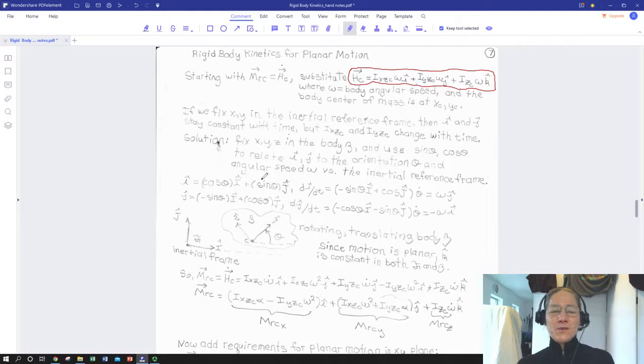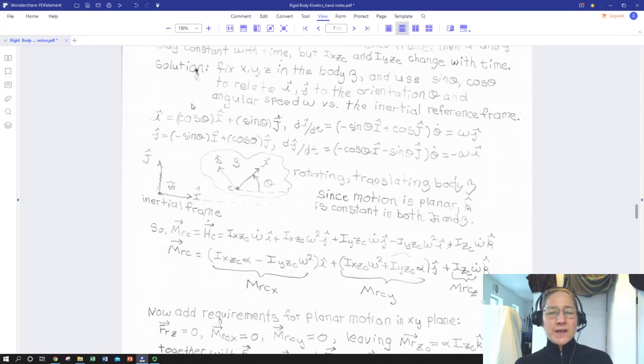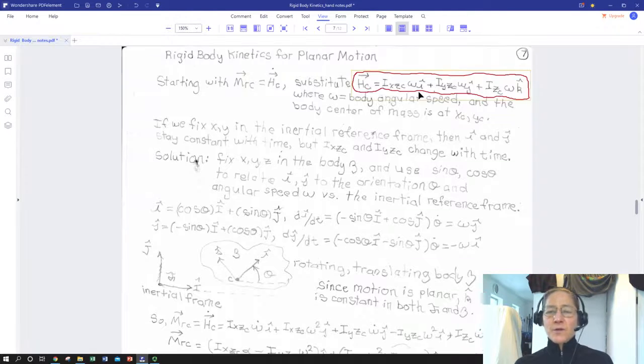So what we're going to do is fix the inertial properties of the rigid body to a coordinate system that is fixed on the body, not the reference inertial frame wherever it is, usually outside the body, but it doesn't have to be. So let's go down and blow this figure up a little bit. This is a bit esoteric, but super important. Because remember, unit vectors change if we're talking about taking the time derivative of something with respect to an inertial reference frame.